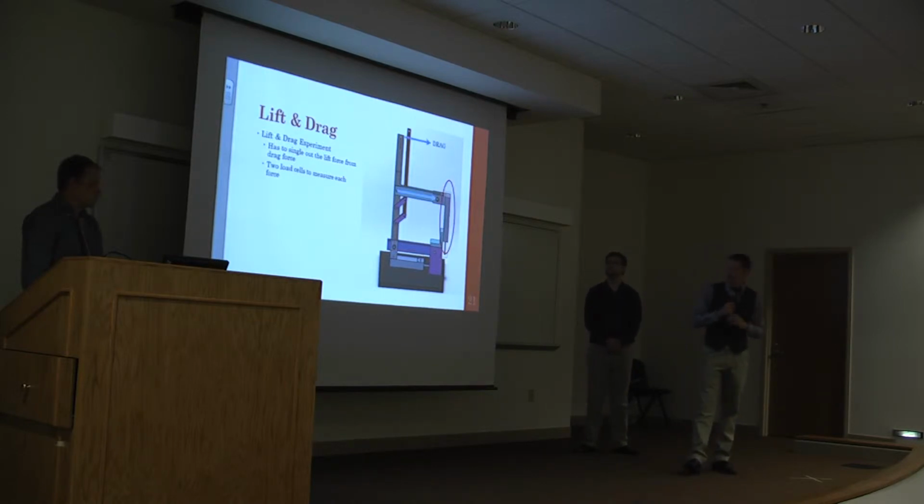Next, in the same respect, we have your drag, which is pushing in the horizontal direction and is able to transfer that force to the load cell there on the right. Lastly, for the design, we have our angle of attack. This allows you to change the angle of your airfoil and get different lift and drag from that.